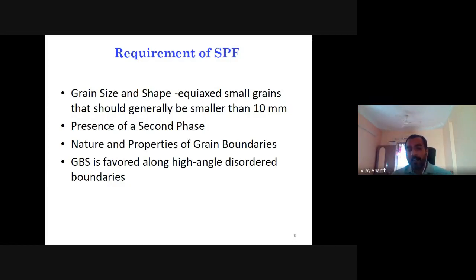We are heating the component to more than 400 to 500 degrees centigrade. What will happen? The second phase, this magnesium and silicon, starts to melt, right? It is not fully melted. It is like a very thick metal, just starting to melt, so it is very much softer. So the second phase, Mg2Si, will form. Magnesium silicide will be formed as a second phase.